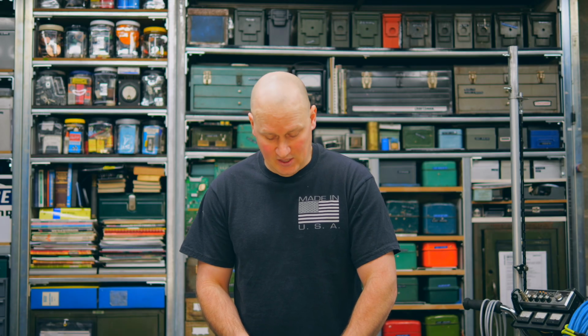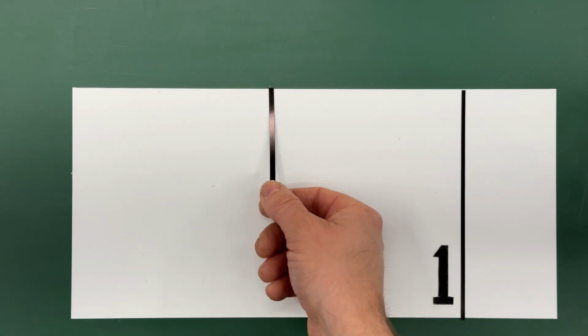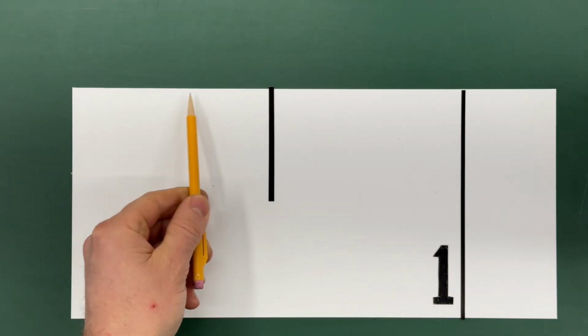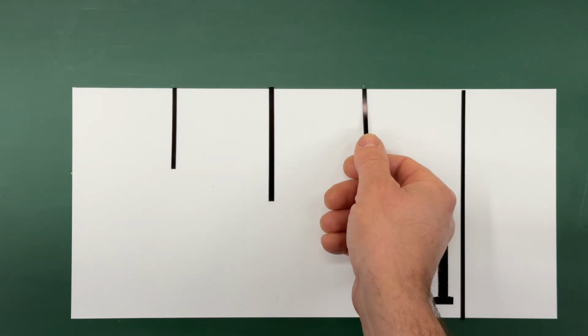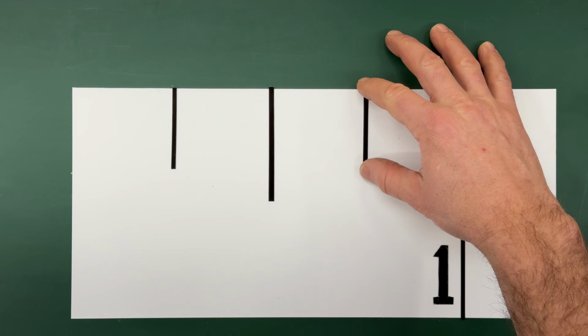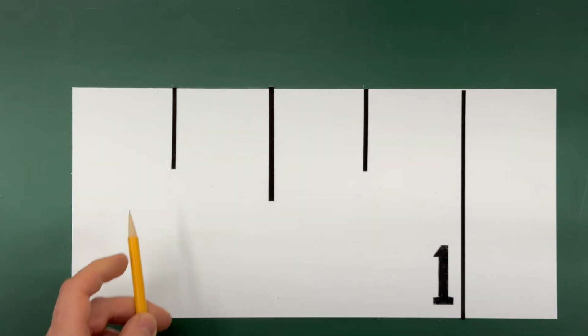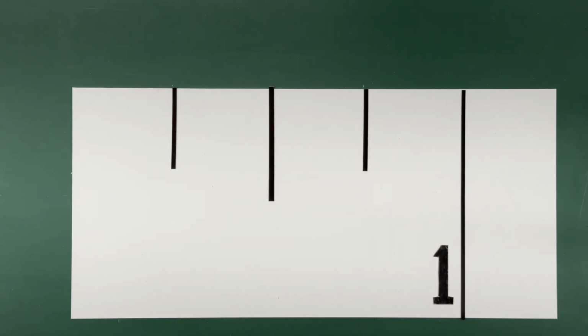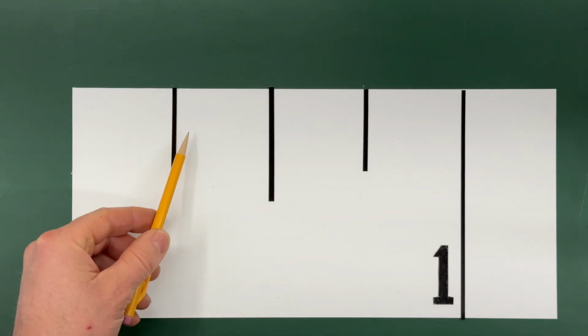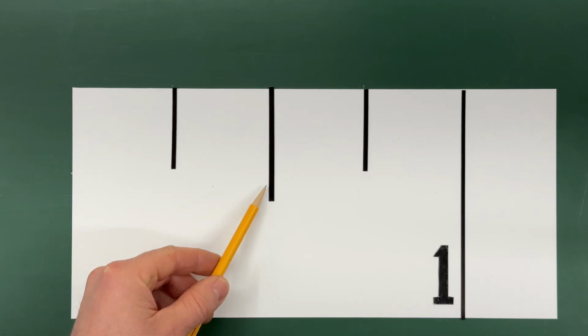Since the inch is always evenly divided, we will start by dividing the inch in half and putting a graduation mark at the half-inch point. The half-inch mark is the second longest fractional graduation mark on the scale, second to the full inch mark. Now we divide each half-inch section in two, leaving us with an inch that is divided into quarters, with marks at 1/4 of an inch, 1/2, 3/4 of an inch, 4/4 of an inch, or the whole inch. Notice the marks at the quarters are shorter than the half-inch mark.